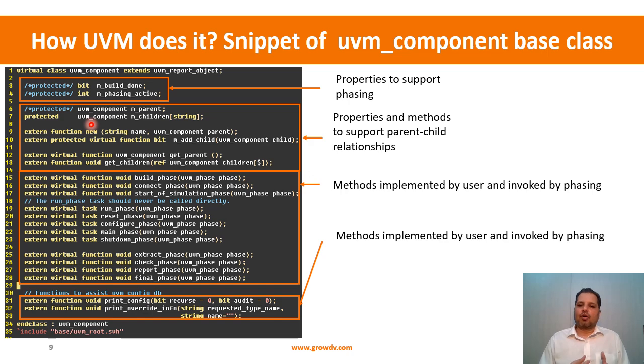Because it's an active component that stays throughout the duration of the test, it establishes a hierarchy, and those hierarchies are all represented over here. Whatever parent-child relationship comes in the UVM based hierarchy, it all gets stored over here. There are additional properties and methods provided which store that information, and that information is what we eventually consume.